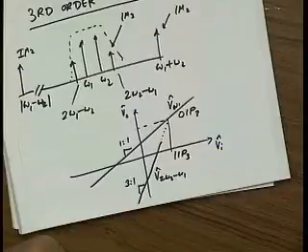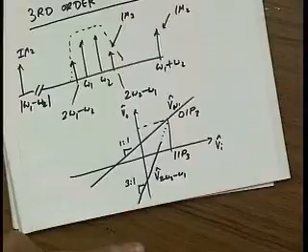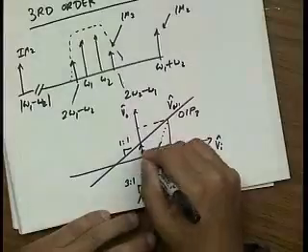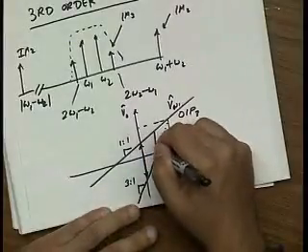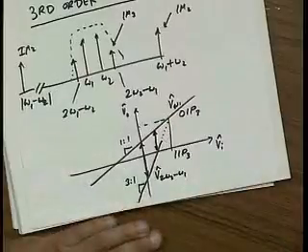Well, let's say the IP3 point arbitrarily is at 0 dBm. Let's say you need 100 dB of IM3. What's the maximum input power that you can put in? Anybody? So if this is the IM3 at a given input power, if I move over 10 dB, how much does the IM3 decrease?